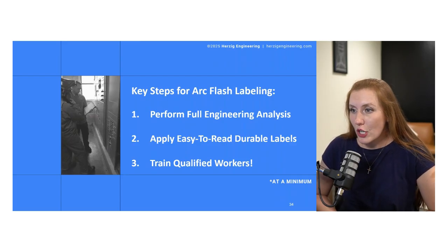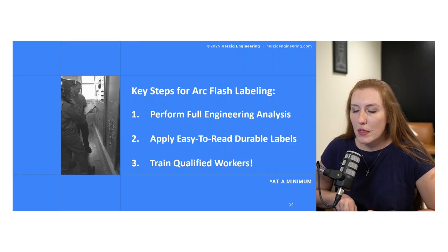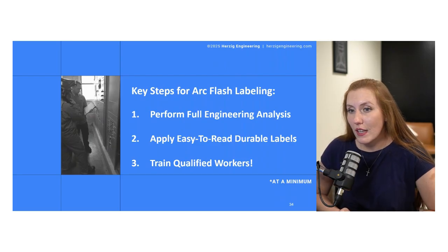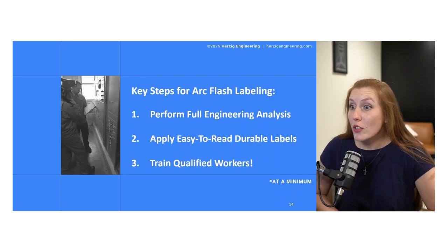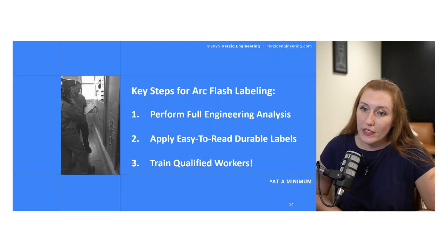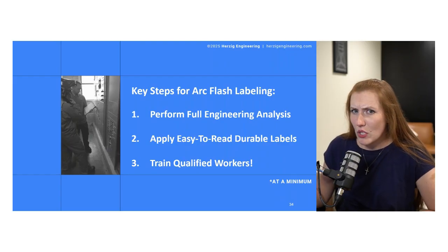Apply easy to read, durable labels. It does need to be able to withstand the environment that it's in, not just paper and packing tape. I've seen all kinds of things. And train your qualified people on how to read the labels and use the information, not just read it.